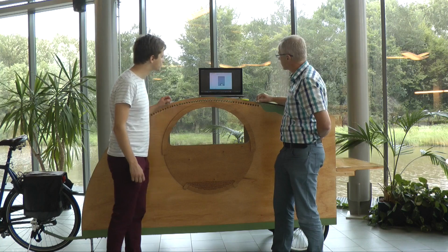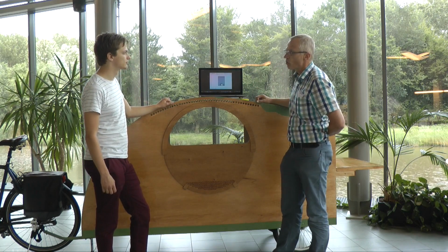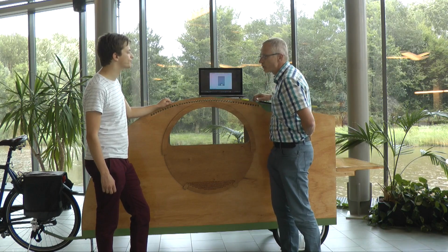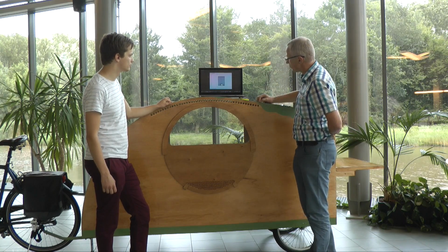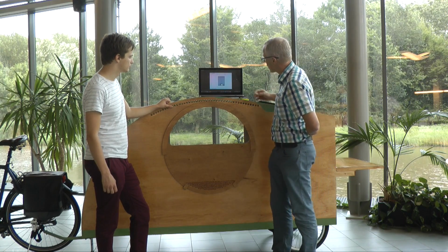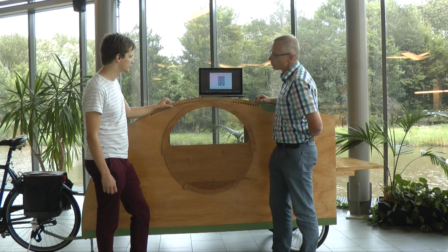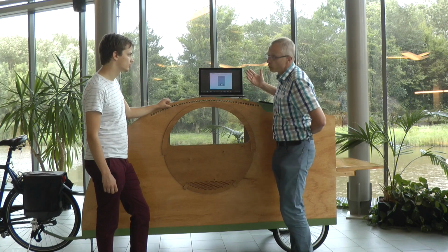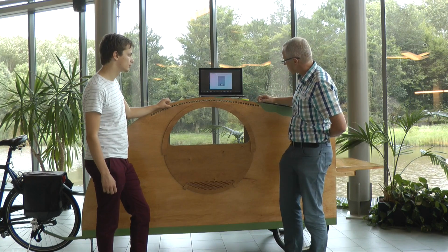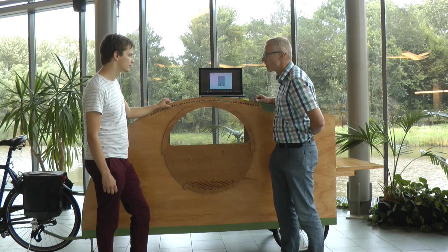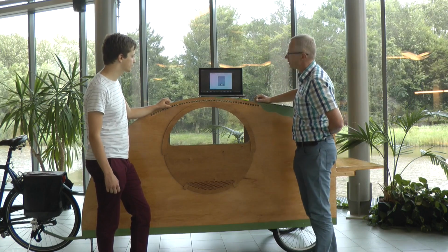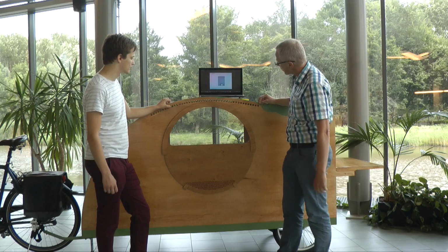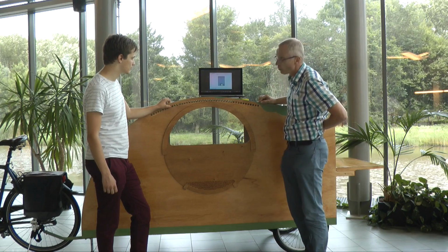Also, if you have a high resolution you have to store a lot of data, and the computational work will be more involved. So we like to keep the number of triangles low, but on the other hand we like to have accuracy, and therefore we would like to have a lot of them, and make them small. So there's always a trade-off between accuracy and the size of the problem you can deal with. For this simple case, this is quite feasible.